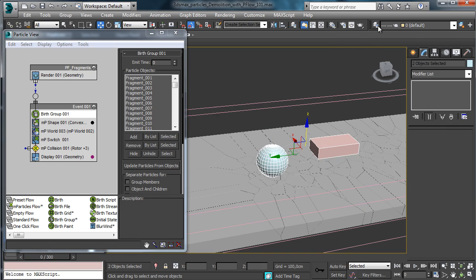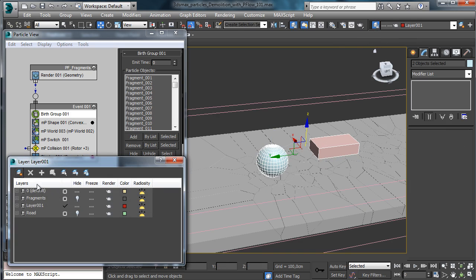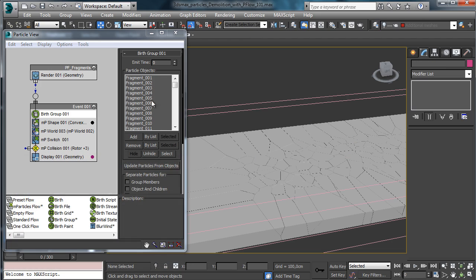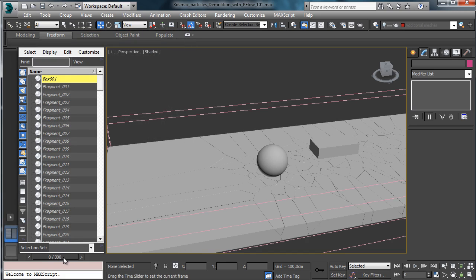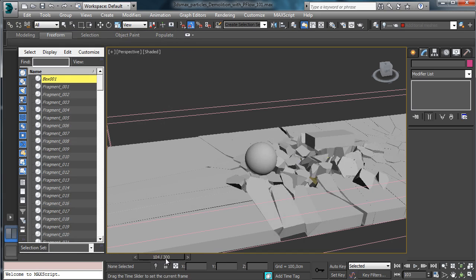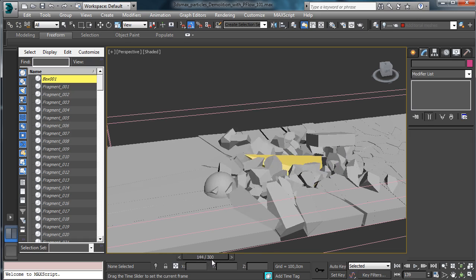Now we can pick this object, put over a layer, let's say additional meshes, set to hide, and there in the build group we have update. So now we have the meshes over, and if we go to simulate, you see that we have the braking.